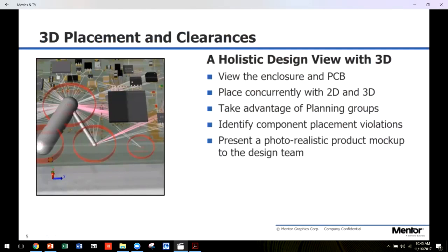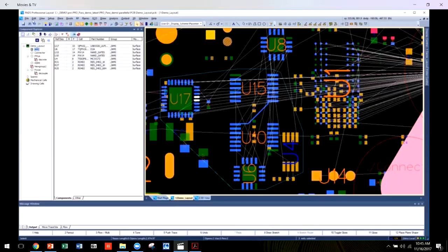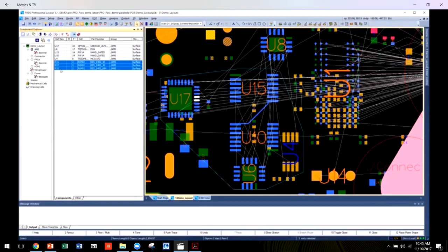The circuit engineers can create component groups in Designer, which the layout designer can place, append, and use as guidance during floor planning and placement. You can quickly view, sort, and organize a list of the relationally structured components, preserving the engineering design intent to guide placement. You can quickly append these layout groups and create new hierarchical planning groups as you deem necessary during the planning phase, and push that information right back to the schematic.